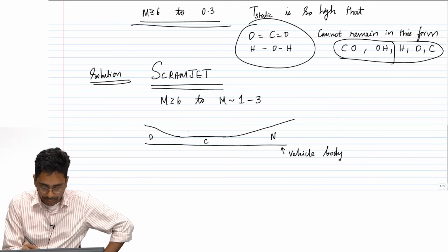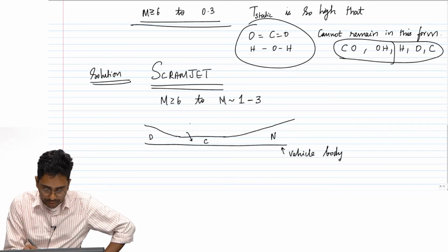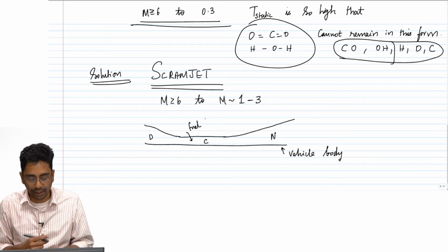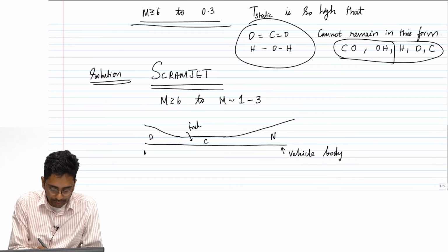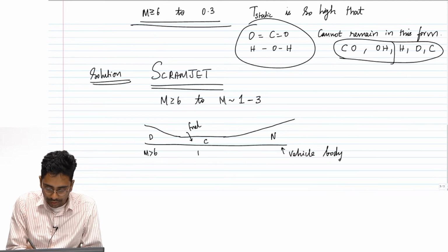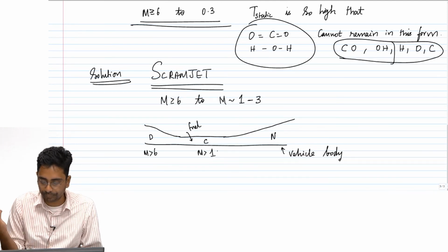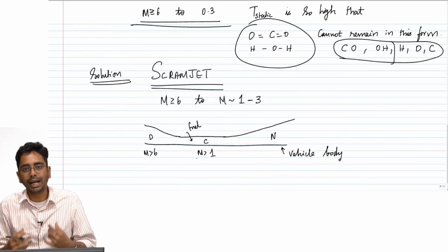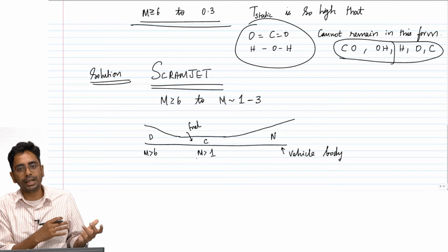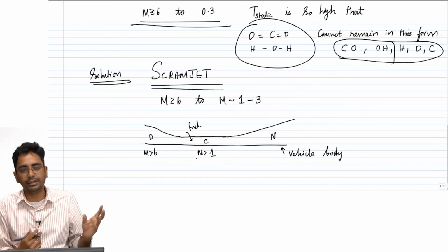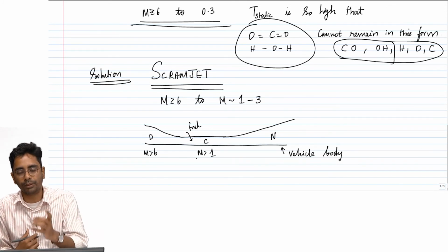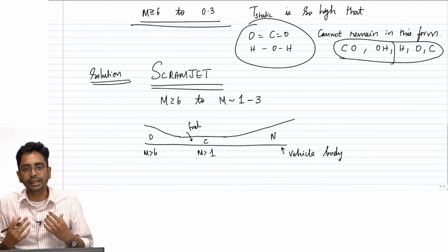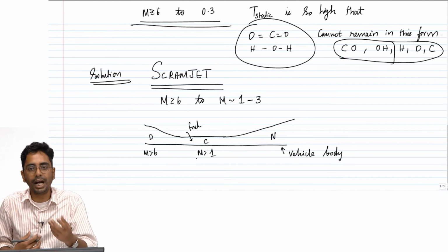And you add fuel, and if you expect enthalpy addition to happen because of fuel addition, the Mach number here is greater than 6, here also it should be greater than 1. So combustion happening, you have not decelerated from Mach 6 to Mach 0.3, instead you have decelerated from Mach 6 to maybe Mach 1.5 or Mach 2, so that the static temperatures are not high, so that addition of fuel will lead to addition of enthalpy.